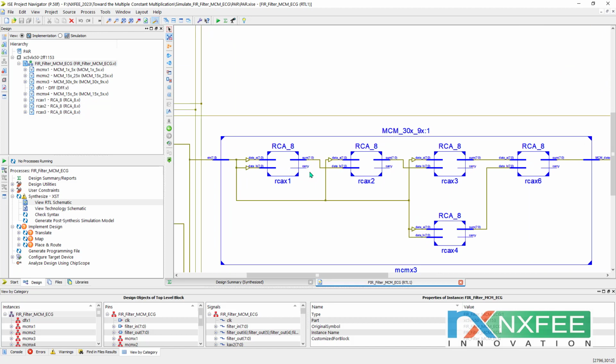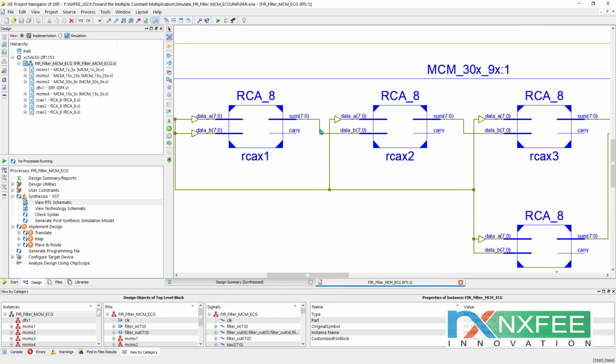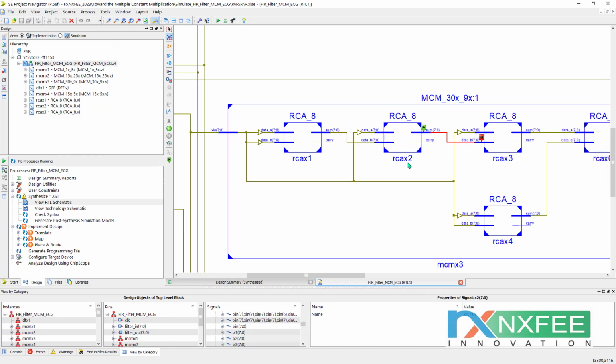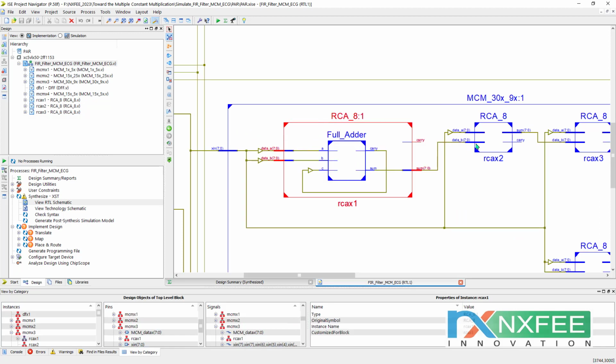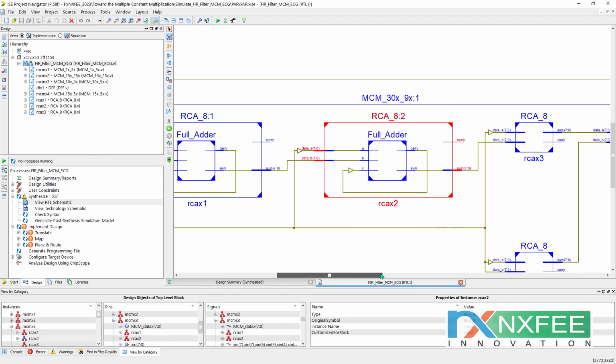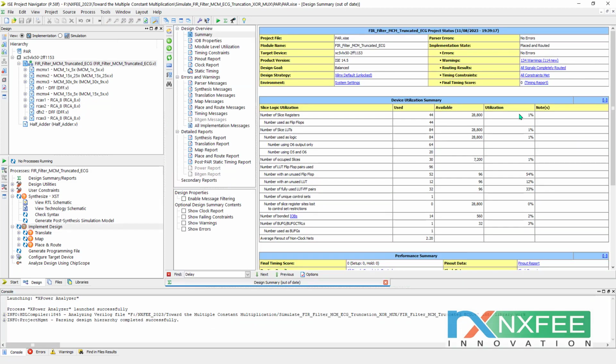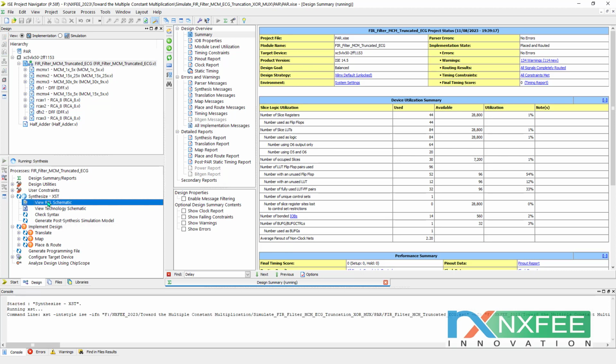Here all the ripple carry adders (RCA) are used at 8-bit level only, not at 4-bit level; the truncated method is not applied here. This RCA is supported with full adders. After that, we have the proposed synthesized report. Here you can analyze the number of slice registers, LUTs, occupied slices and IOBs, and you can analyze the RTL schematic.